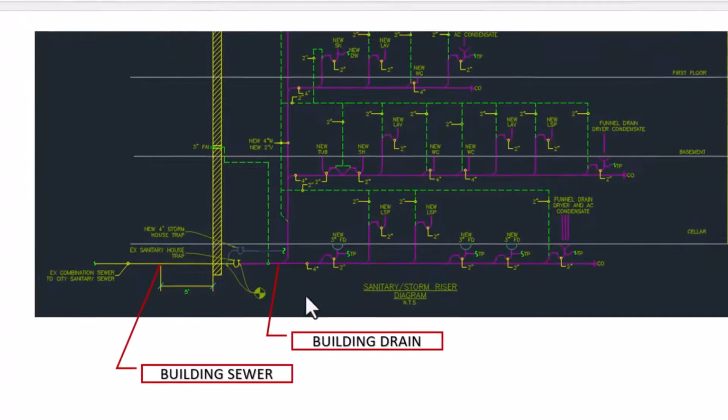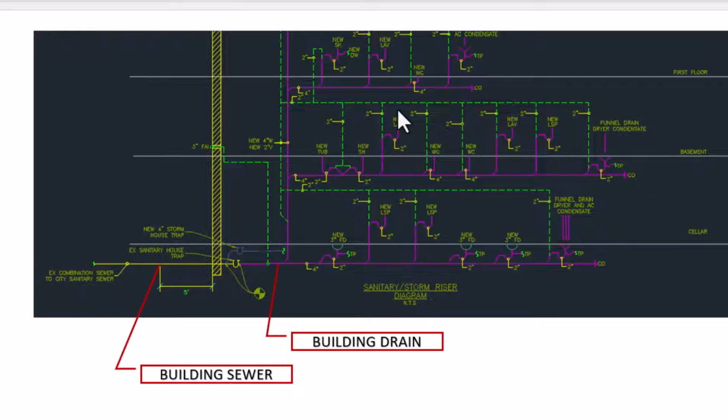So it seems like waste piping is just kind of like a commonly used term to represent both waste piping and soil piping. So somebody might call this pipe a waste pipe where it contains fecal matter from this water closet. So by definition in the plumbing code, this would be called a soil pipe. So generally people will just call a waste or soil pipe just a waste pipe.